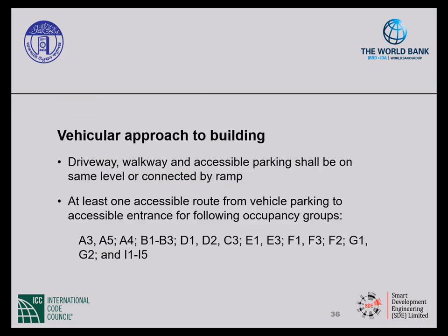Vehicular approach to a building. To facilitate persons with a disability approaching by vehicles, the driveway, walkway, and accessible parking surfaces within the site shall either be merged to a common level or connected by a ramp.